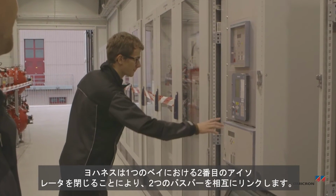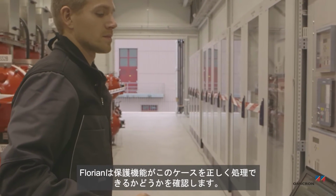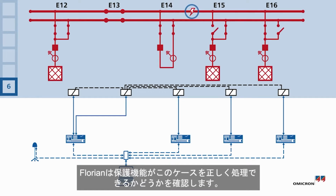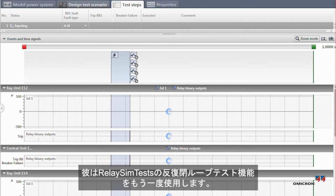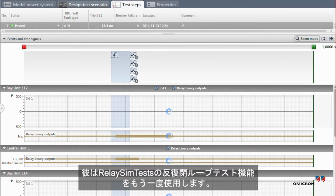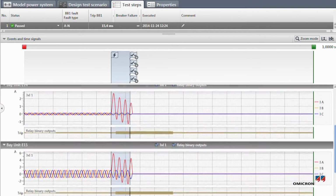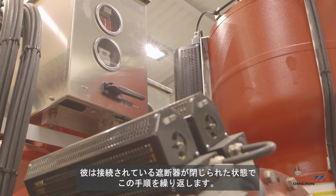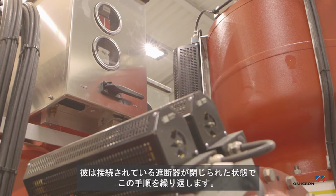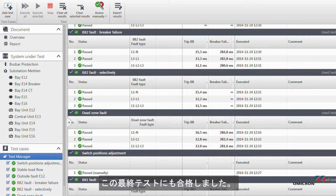By closing the second isolator of one of the bays, Johannes links the 2 bus bars to one another. Florian checks to see if the protection can also handle this case correctly. Once again, he uses RelaySimTest's iterative closed loop testing feature. He repeats this step with the circuit breaker connected in a closed position. The protection has also passed this final test.